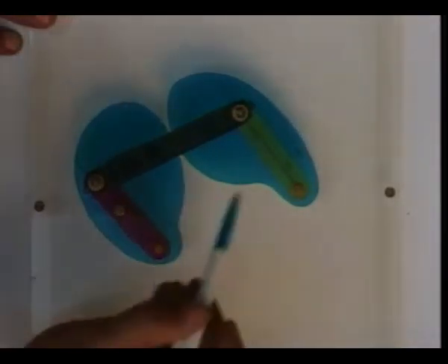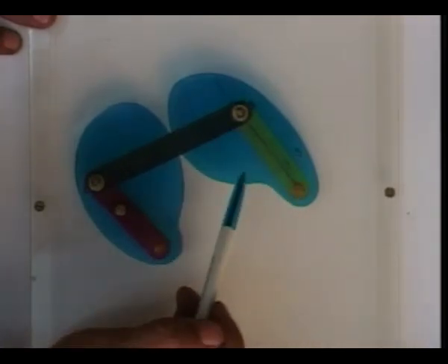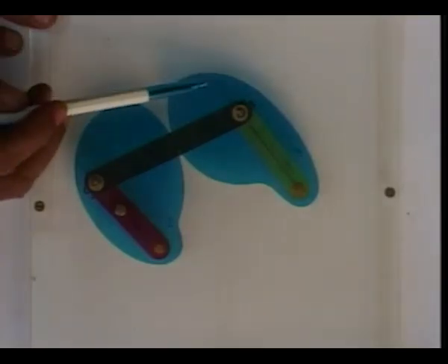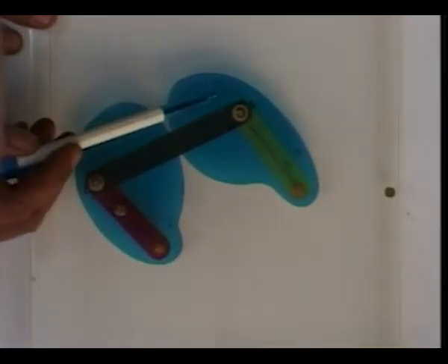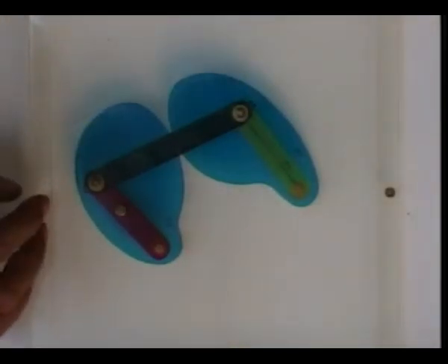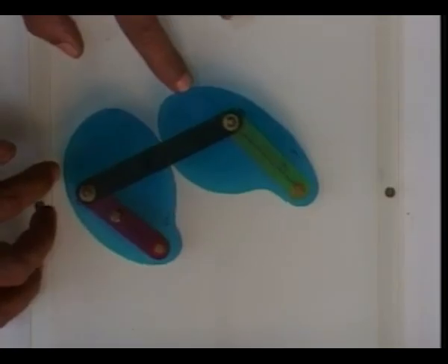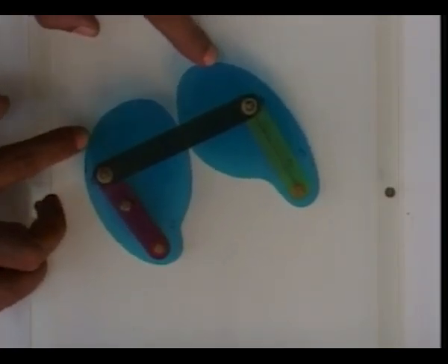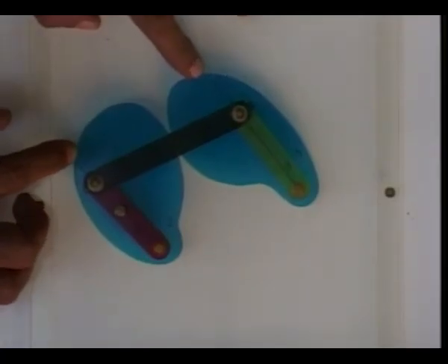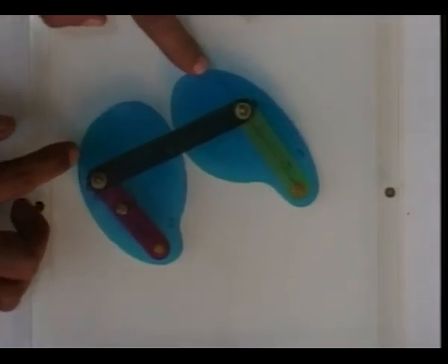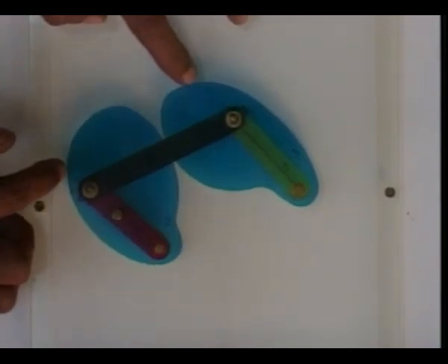To distinguish the movement of body 3 in the lower pair linkage and body 3 in the higher pair mechanism, let us notice these two lines: there is a red line on this body and a blue line on this body. Around this point, these two lines move almost the same way, because the velocity and acceleration relationship between the original higher pair mechanism and the equivalent lower pair linkage is just the same.